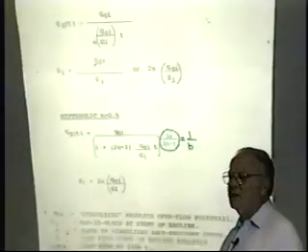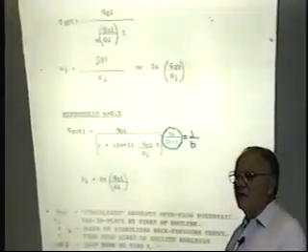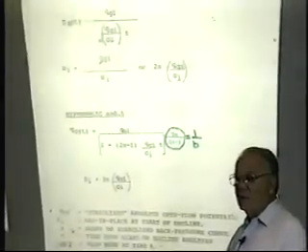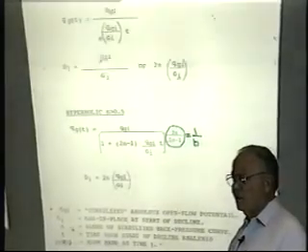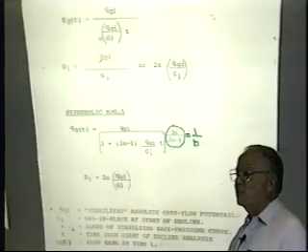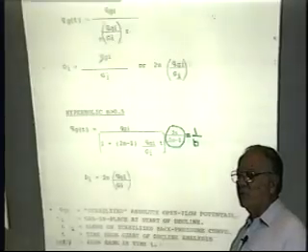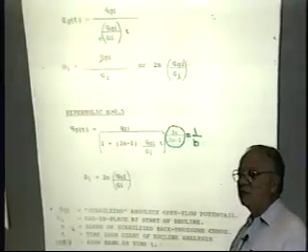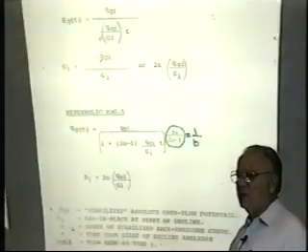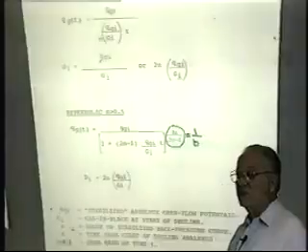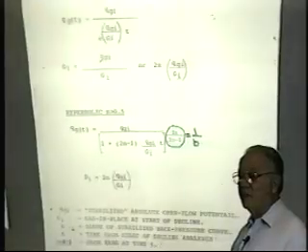This bothers people, but it really simplifies the derivation. I already told you, if you're going to worry about it, I'm not going to flow against a zero line pressure. As a prudent operator, you're going to flow against the lowest flowing pressure you can, and if it's a function of a difference in pressure squared, whether it's 0, 100, 200, or 500, the rate's going to be virtually the same. You have to understand that.